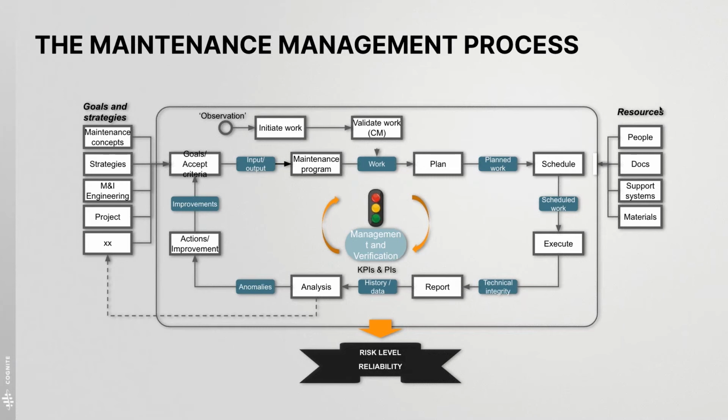However, it's also very common to start establishing a maintenance strategy during the plant life cycle. The underlying data used in this process is either from plant operations or from databases of historical failure data where available. The next step, after you have set the maintenance regime and maintenance strategy, is establishing maintenance plans, both preventive and corrective.